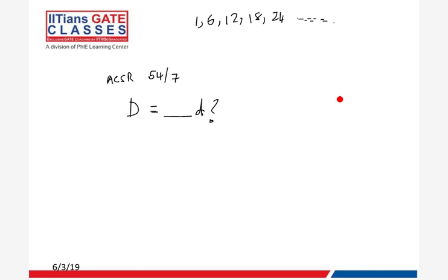You have the pattern on the top. Just find out how many layers of aluminum and how many layers of steel, find out how many total layers there are, and calculate the effective diameter.